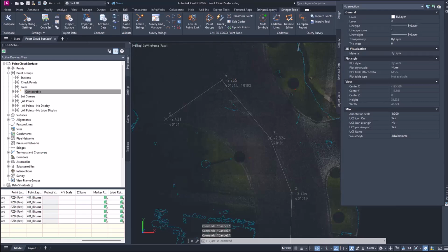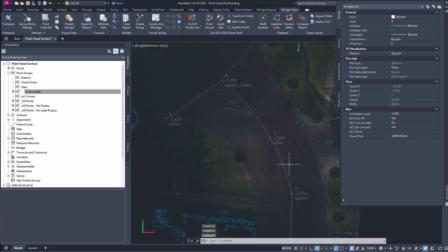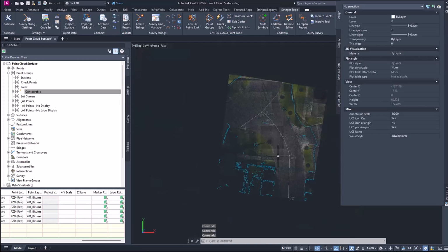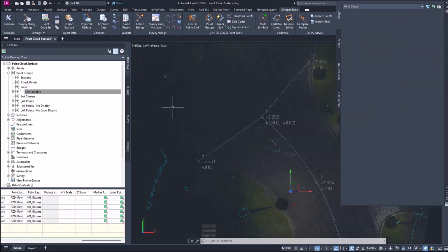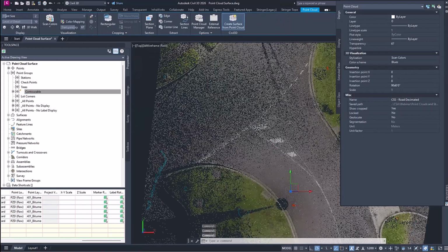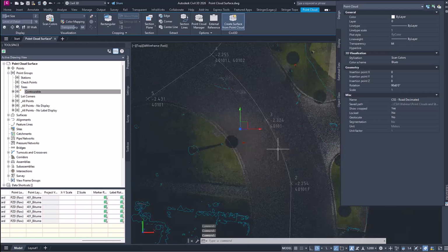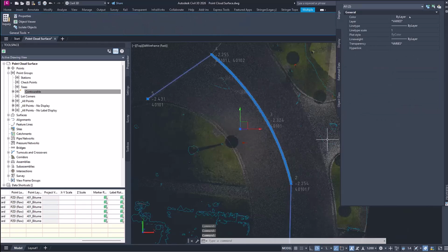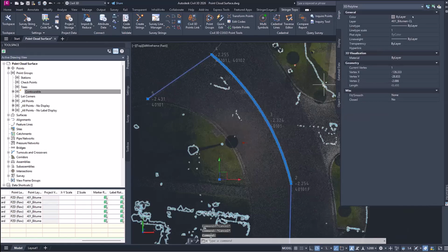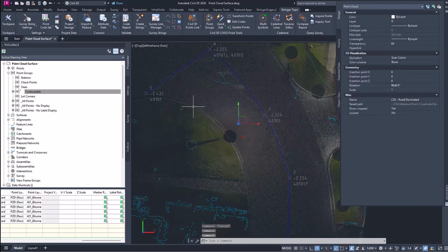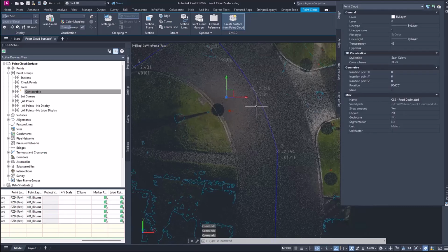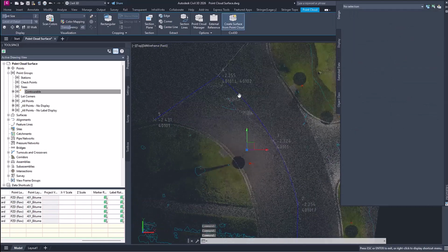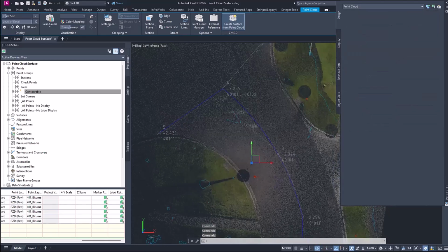And then if we go back to Stringer and we go update strings, you can see it's now got that curve. So it's curving around there. We've got it connecting both of those up at once. We turn back off the transparency. Let's change the color of that string so we can actually see them a bit better. We can see it's hugging that center line pretty accurately for me putting in those points very quickly.